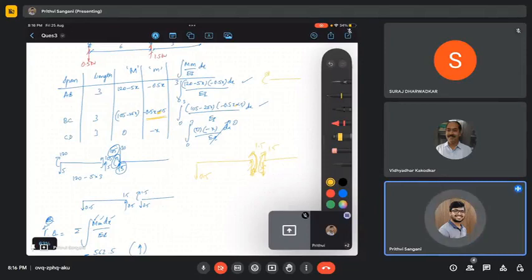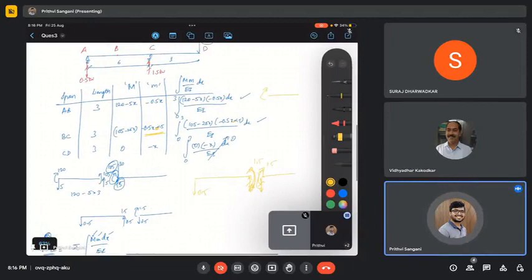Yes, but anyway, you need to remember that we are only writing the bending moment diagram or bending moment equation for each span, so that our calculations will be easy. We can easily find out from 0 to that span. We'll just break the beam into different spans, and then we'll write down the bending moment diagram as our bending moment equations.